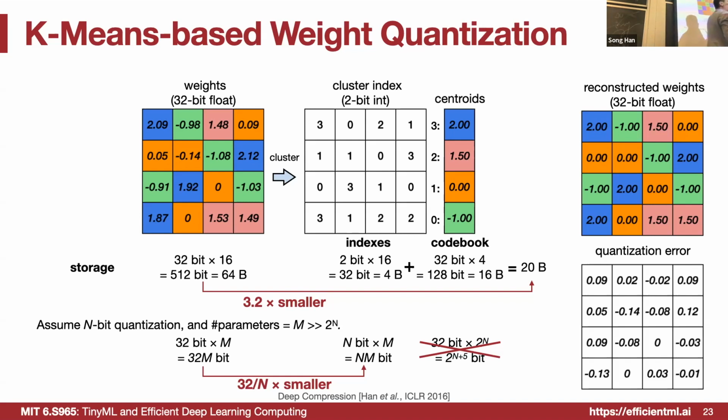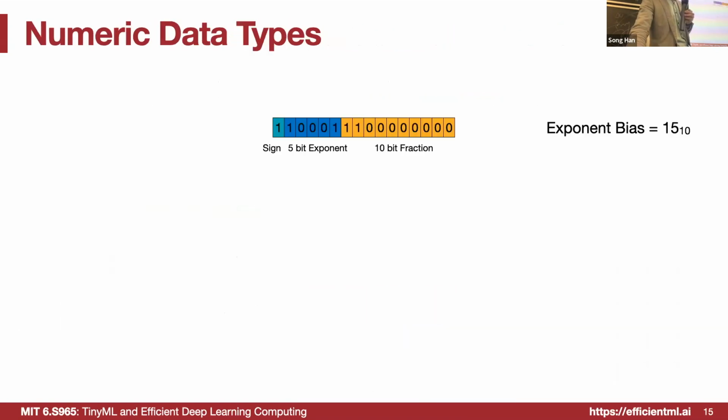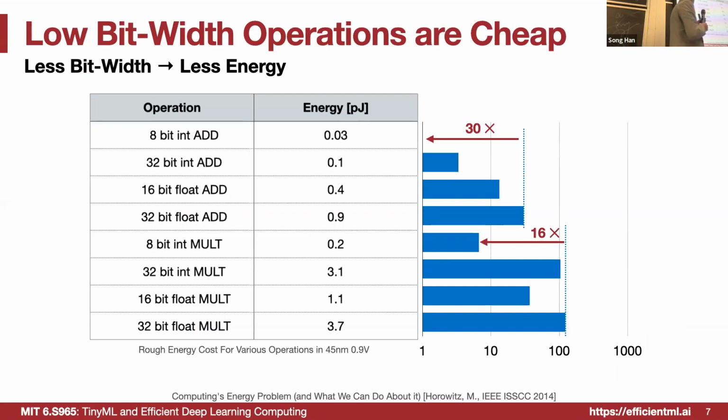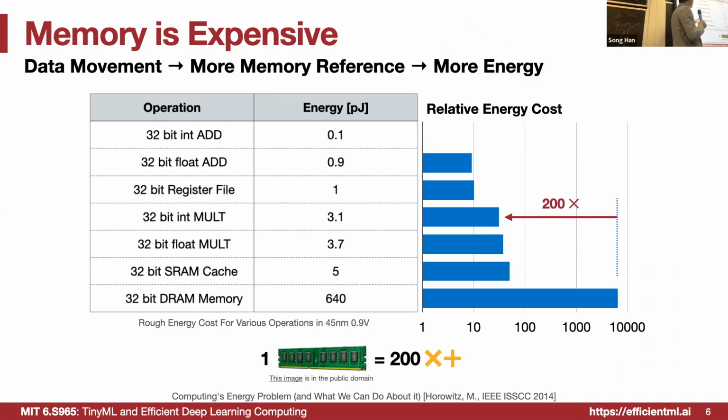That's a good point. So we are exactly doing one level of indirection. But here, like we mentioned in the first part of the lecture, data movement is expensive, computation is cheap, right? Here we need to only dereference from a register file that has only 4 entries, which is very cheap, compared with having to go to the main memory to fetch such a large amount of numbers, right? Referencing a register file, which of course will be in the cache, is much cheaper compared with going to the main memory, since we have 32 bits. Now you need only 2 bits. So that trade-off is worth it.